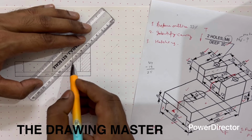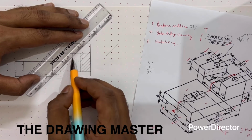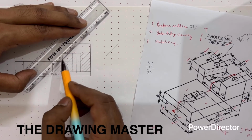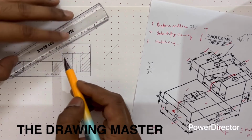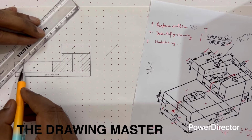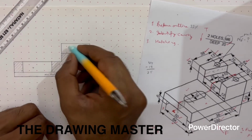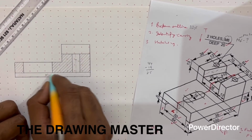You have to keep a little bit of patience here. You can see that with patience I'm drawing these section lines. These lines are the section lines, and I'm using a continuous thin type of line to draw the section lines. This is solid area and this is the last part. Now this is the sectional front view of the object.